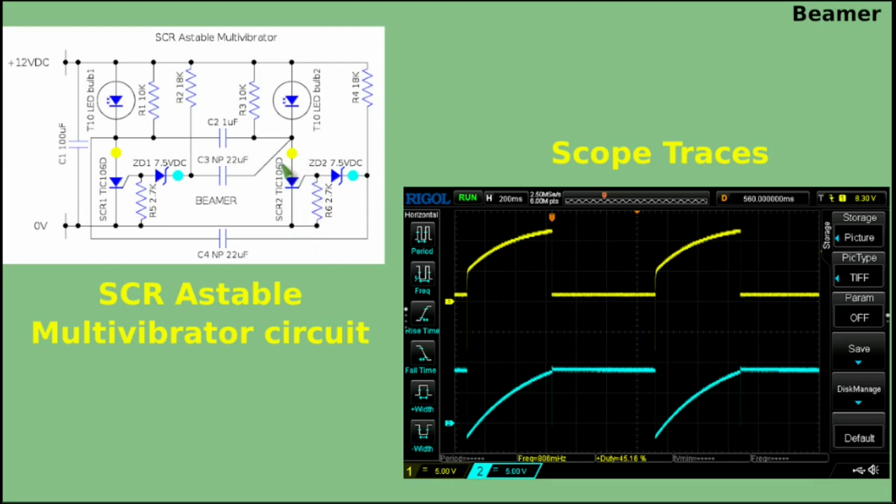So in this circuit, each SCR has 2 of the 3 conditions that I said would turn an SCR off. So you've got the security of making the gate negative to turn off the SCR and a negative spike on its anode to also turn off that SCR. So it has 2 means of switching this off, giving this very good security in turning this off. So they never both turn on at the same time.